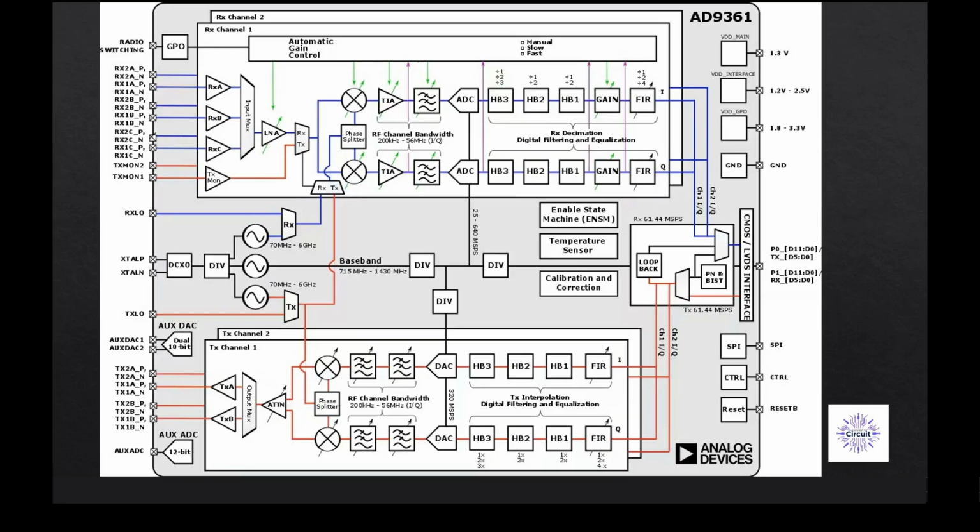But for now, we just want to understand that beamforming can be either on the high frequency side or the low frequency side. On the high frequency side, basically after the signal is up converted, assuming that both channels have equal phase between each other, we can add a time delay or a phase shifter here to change the phase of one of the channels.